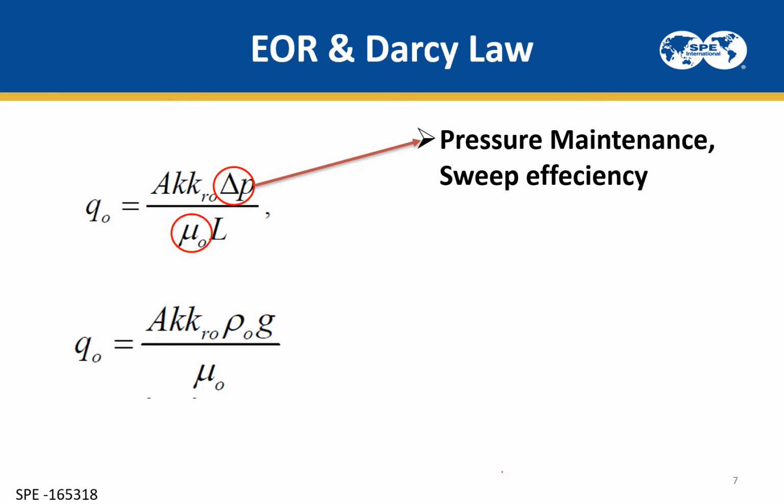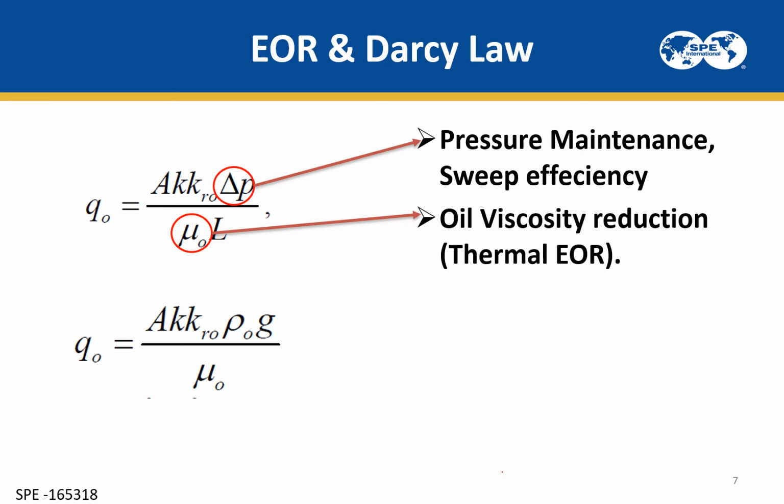When we are focusing on oil viscosity, mainly the reduction of oil viscosity, it leads to improvement of the mobility of the oil, and accordingly the production of the oil will be increased. In this case, we are talking about thermal EOR, where the main function and mechanism of thermal EOR is to reduce the viscosity.